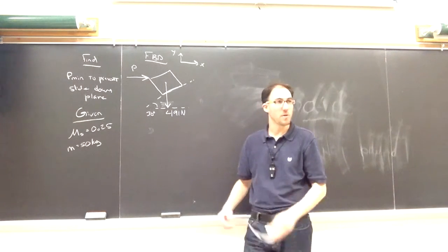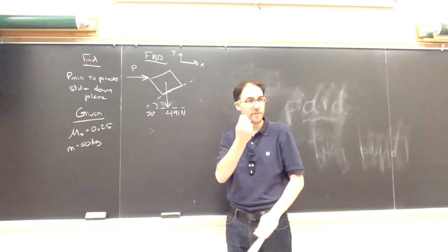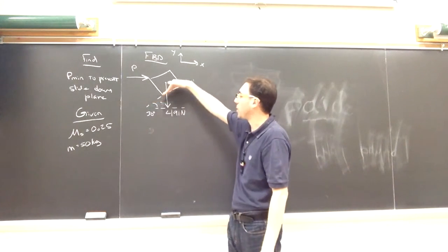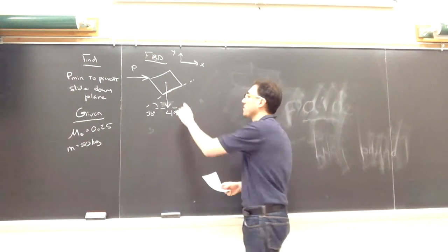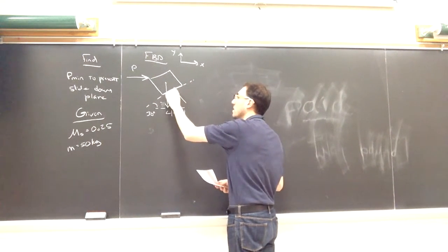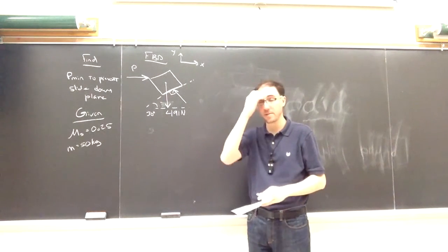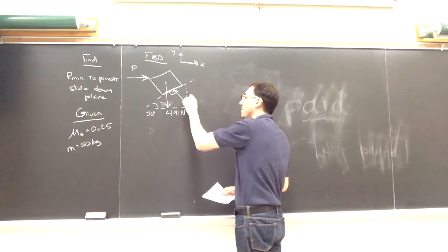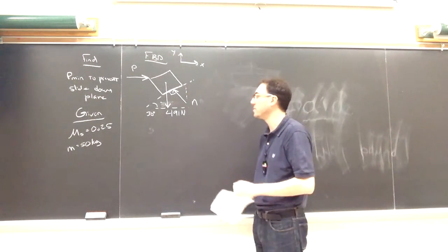And the normal force will always be acting normal to the surface of contact. In this case, that's a 30-degree angle. So the normal force is not up. The normal force is going to be at this angle that's normal to the interacting surfaces. So that's some normal force. I'll just call it lowercase n, so I don't confuse it with newtons.